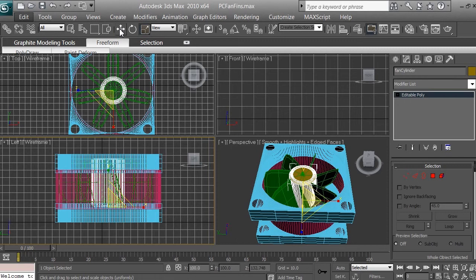Okay, click on the select and move icon here. Just watch the previous video, so you're going to see whenever we use this tool, select and link, to connect the fins to the cylinder. So right now it's acting as a group. Whenever I move the cylinder, the fins move to the same positions, and whenever I move or rotate the cylinder, the fins just repeat it as well, to rotate or scale or move to the same position as our cylinder, because it's basically linked to it.